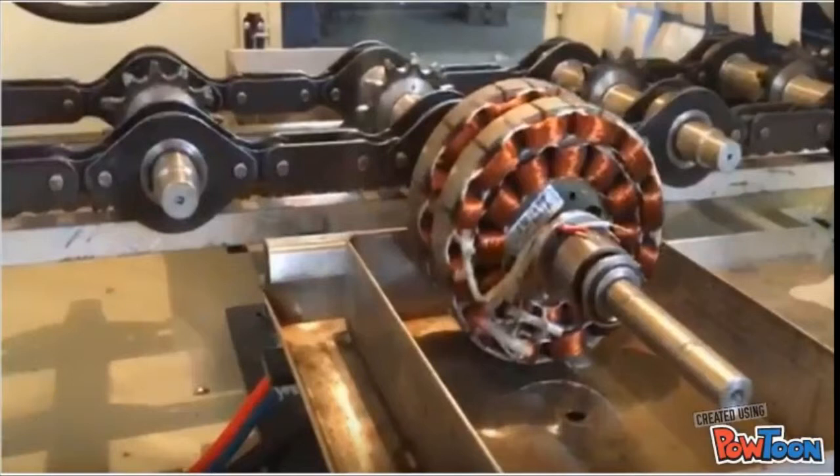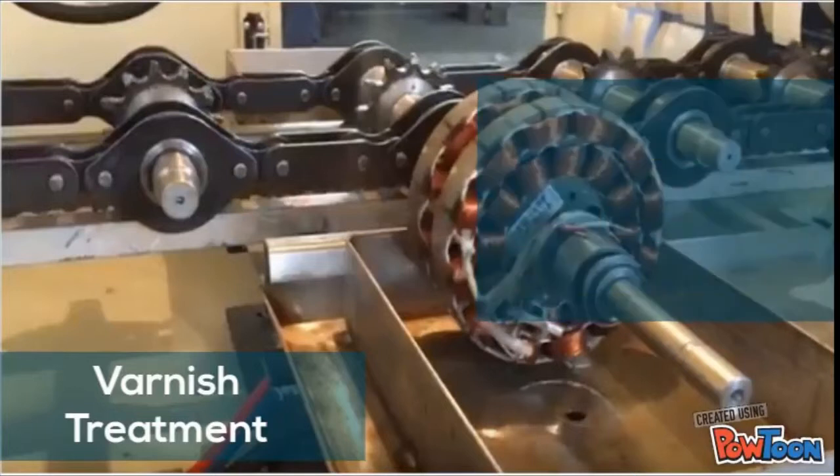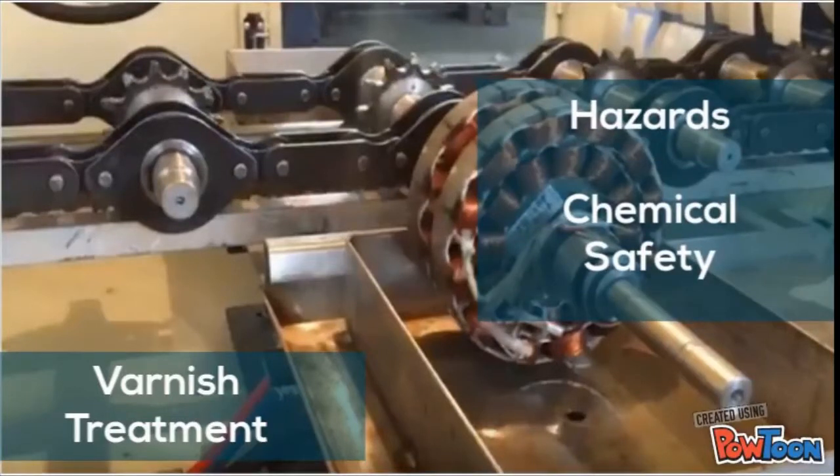And then afterwards, this will proceed to the varnish treatment, where a liquid preparation that, when applied to a surface, dries to form a hard, lustrous, typically transparent coating is applied to the stator. The hazards that can be found here include the varnish and the empty boxes and cans, which are classified as safety and chemical.